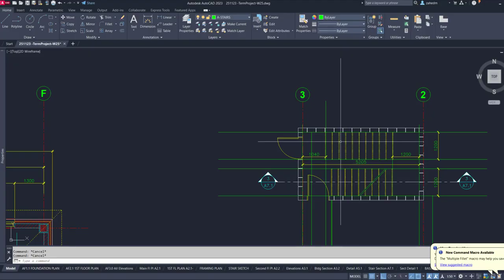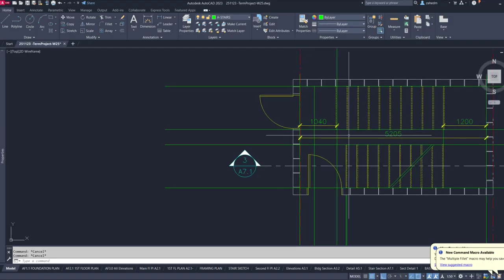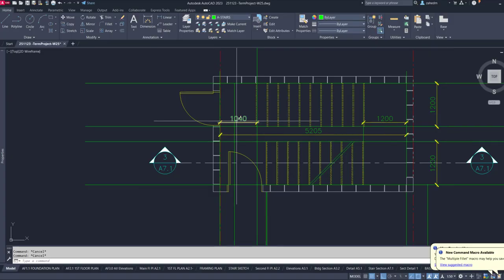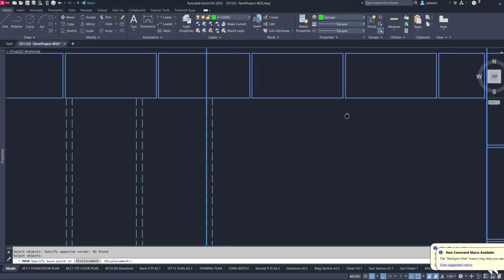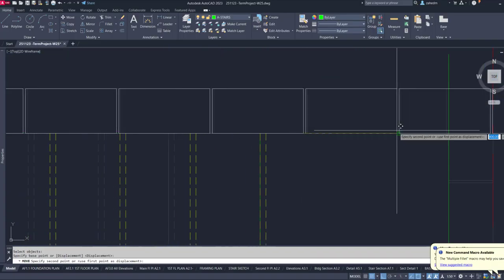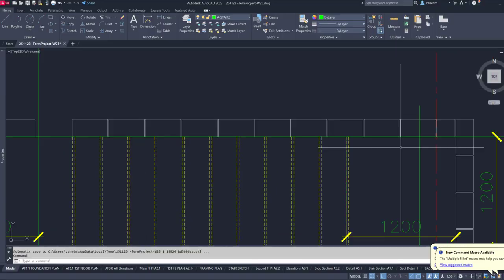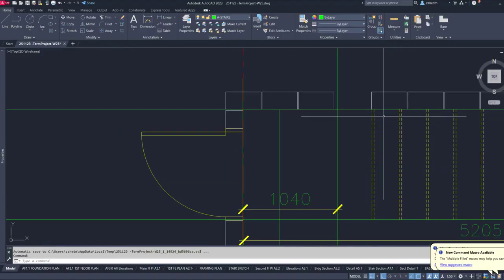To be honest with you, I don't like this number. The reason I'm saying is because it's less than the width of my stairs, which is 1200, and that's not common. So normally the depth of the landing should be equal to the size of the stair width. So in this case, I am 150 short. What I would like to do is, let's move everything. Let's move all the steps and so on. At least one complete block. So here is one complete block, and then I'm going to add that.